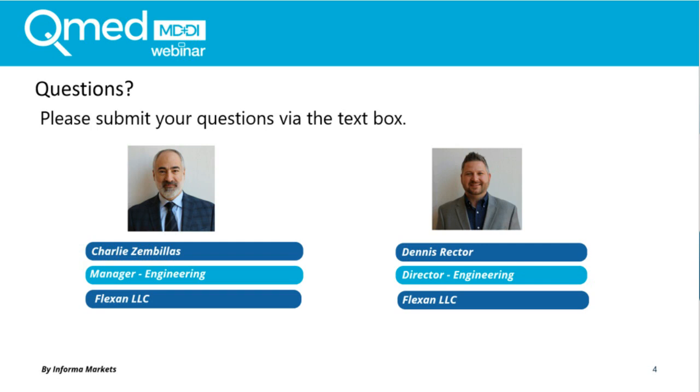Actually, LSR cannot be extruded, so it's not a material that anyone extrudes. The reason why HCR is chosen as a type of silicone for extrusion is because when the material exits the die, as Charlie showed you guys in the video earlier, that material is still in its raw state.